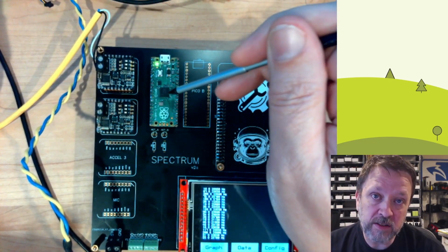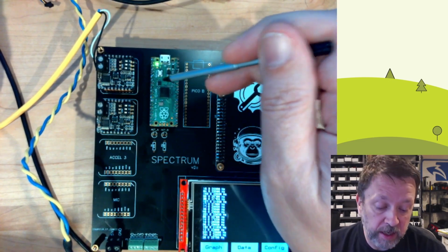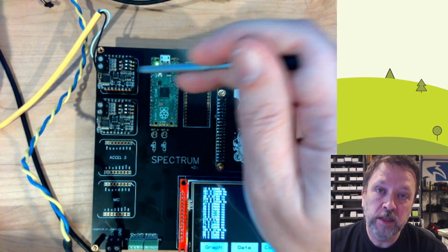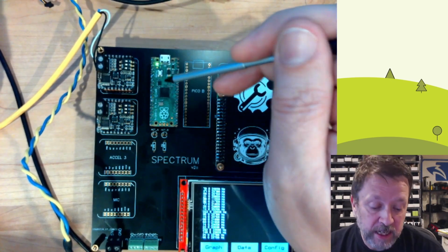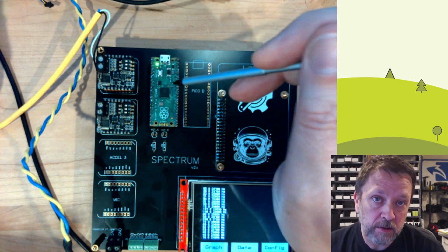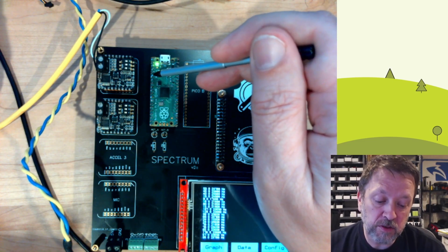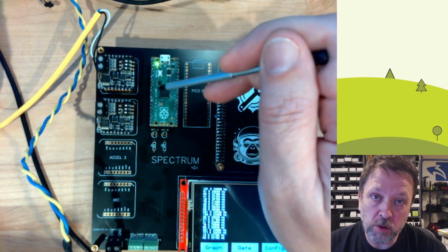The Pico has a 2-core processor on it. So really what's happening is one core ingests this data as fast as it can and does FFTs on that data. It then takes the FFT output and transfers it to a memory block that is shared between the 2 cores.